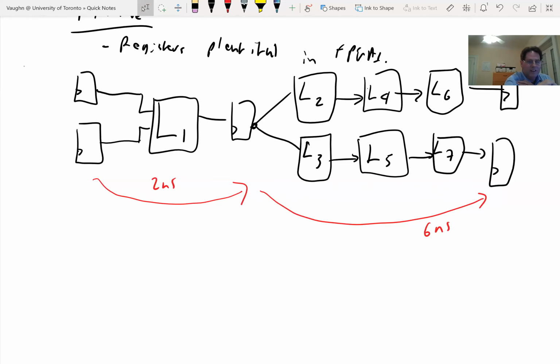No. Okay, so no one likes it. It's imbalanced. Not great pipelining. So I could go back to my HDL and try to move around my registers, or I could just try to rewrite my HDL. There's a systematic way to do this. It's called retiming.